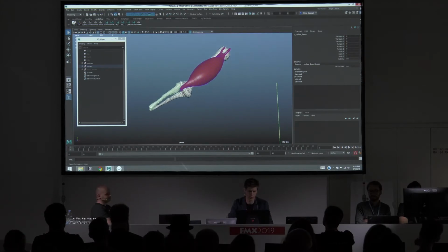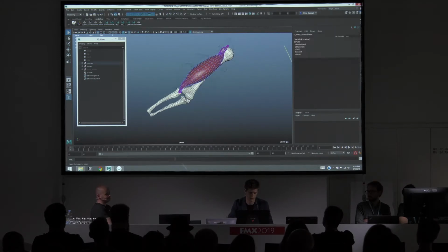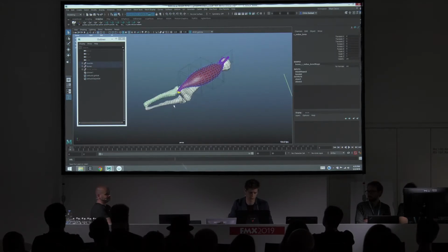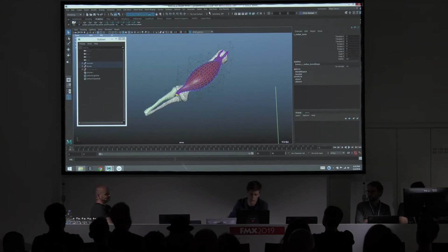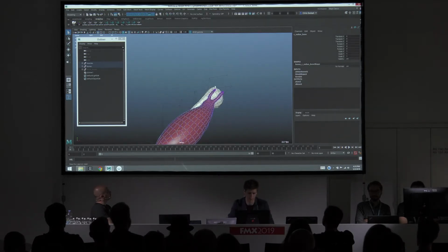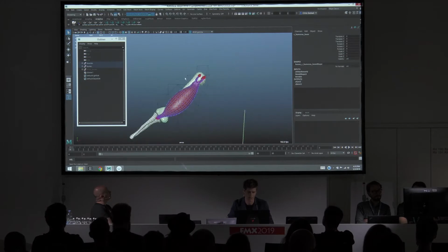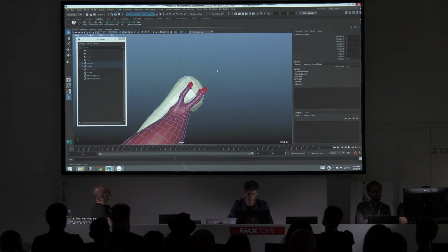And so now what I want to do is attach the tissue to the Ziva bone. I'm going to grab some vertices that represent the origin and insertion of the bones or the muscles, and then I'm going to make an attachment here. With the target object selected, I can come down to add simulation component attachment, and then I'll do the same at the other end. Shift select the bone, oops. And then you'll see that for every vertex that I had selected, it's looked up the closest point on surface